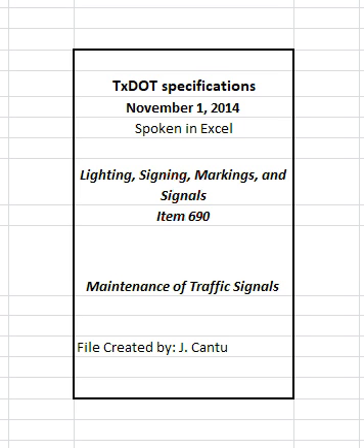3. Equipment. Use equipment that includes, but is not limited to, an aerial device capable of reaching overhead work, trenching machine, boring machine, concrete saw, and digger boom truck. Use only equipment, tools, and machinery in good repair and operating condition. Repair or replace any equipment that, in the opinion of the engineer, may affect the quality of work or safety.